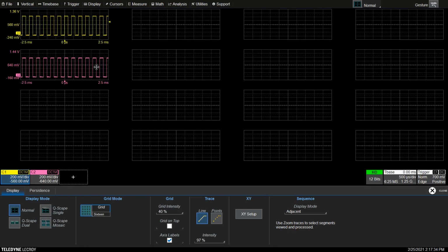Okay, so bottom line again, if you don't want to overlap your waveforms, and reducing the amplitude is fine, which is okay, right? Because you're not making accurate measurements, you just want to see the waveform, then no problem to do that. But if you do want to improve the accuracy, then utilize the full dynamic range of the amplifiers or scope by maximizing the bottom to the top of the waveform within a grid. Okay.